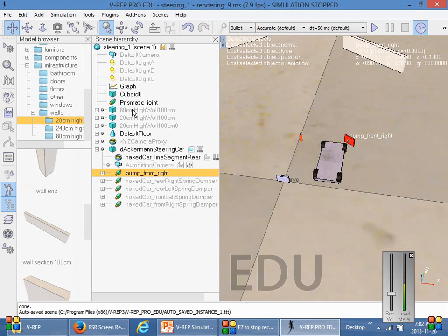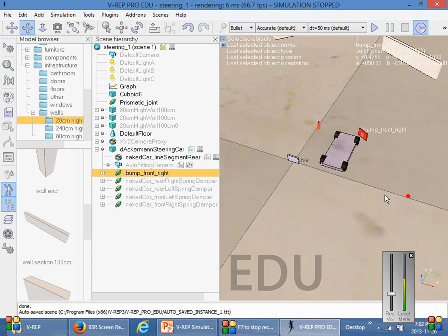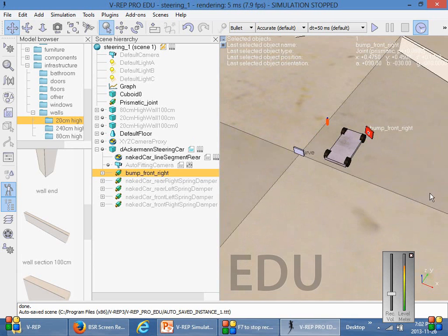So we would like to align them a little bit. What we'll do, we'll try to align them in the Y direction right here. So we select both of them. The order in which you select them matters, so bear with me for a second.